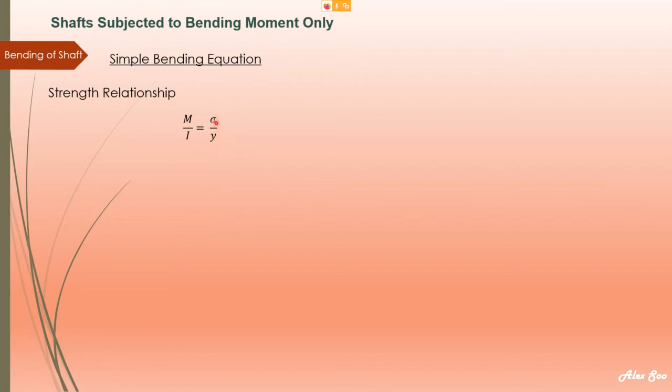If I want to measure the maximum bending stress, usually it is the outside, the outermost layer, that means the external diameter divided by 2. If I take the internal diameter over 2, the bending stress that I get will be minimum. If I take the external diameter over 2, the bending stress will be maximum. Whereas M and I, therefore, should be considered as constants.